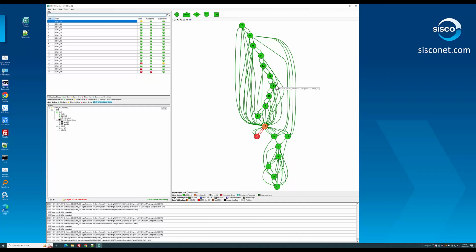We've got a 61850 client connecting to the server and querying its LGOS information. LGOS is a logical node in 61850 that allows a server to describe the status of its GOOSE subscriptions. And so for every green circle here, we can quickly and easily see that that server, that subscriber, is getting all of the information it expects to get. Everything's in good shape.